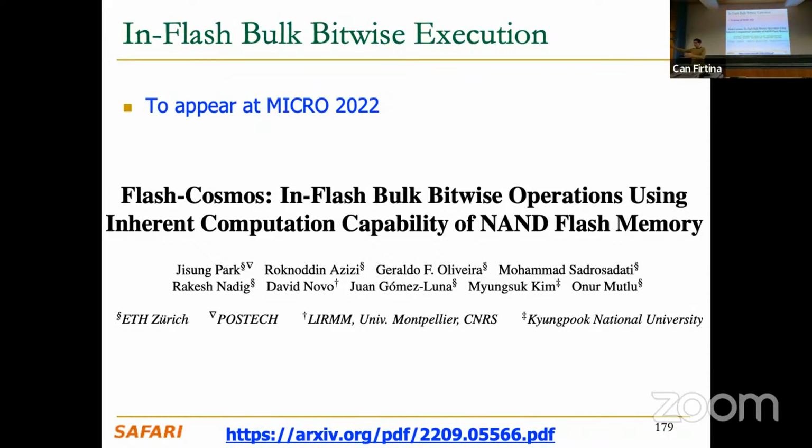Because until now we had the data in the storage in an SSD, and we had to bring the data to memory, and then from memory, bring it to the processor for the processor to compute. We are enabling ways of doing computation in memory, so now we don't have to bring the data to the processor, but maybe at some point in the near future, we will be able to do the computation directly in the storage. In fact, there are indeed some commercial products that already do some sort of computation in the storage, but they are using FPGAs there. It's not like this thing that is more with the NAND flash cells themselves.